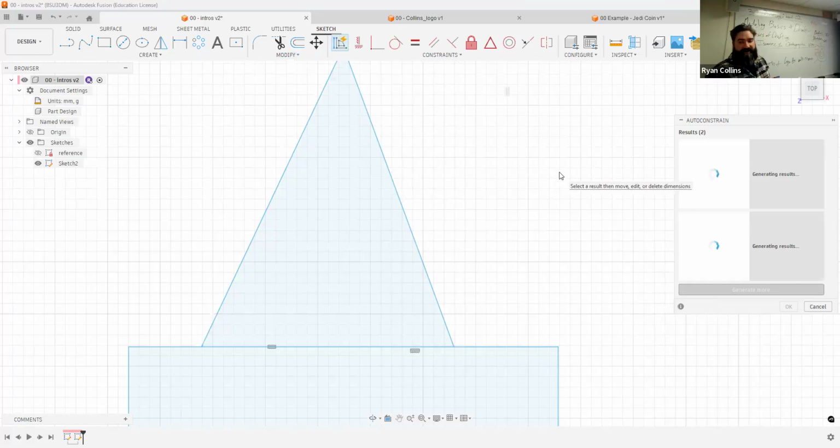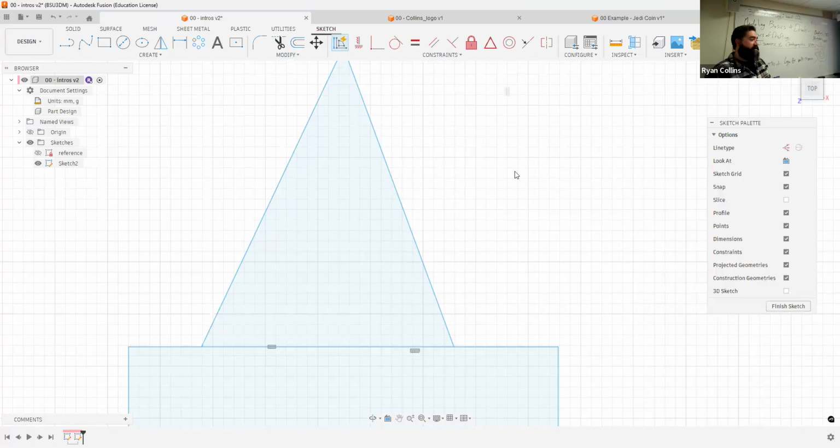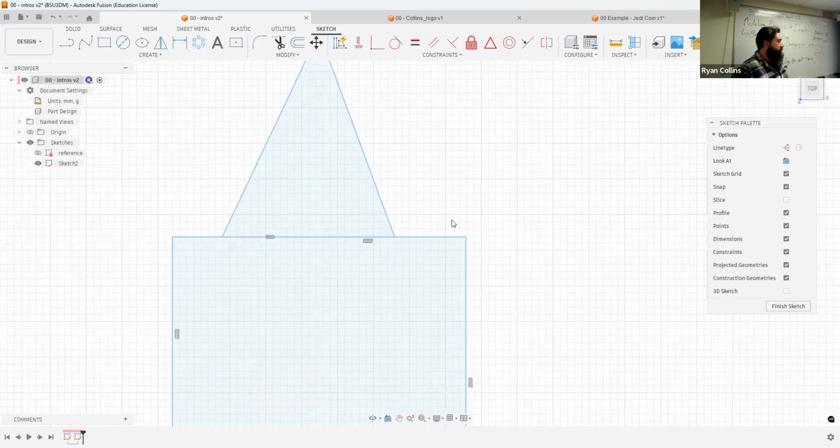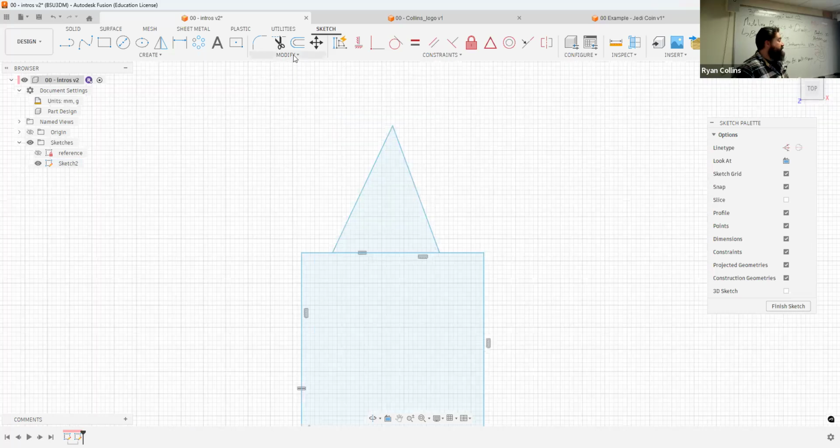It will automatically close. We're not going to worry about that right now because the extend tool is already pretty simple and works really well. Is anybody running into the issue that it's no longer doing the blue highlight thing for you? Or you're working on it? Okay, cool. Usually the extend tool will work the best for that. Or unfortunately, just zooming way in and seeing if you can find the break.